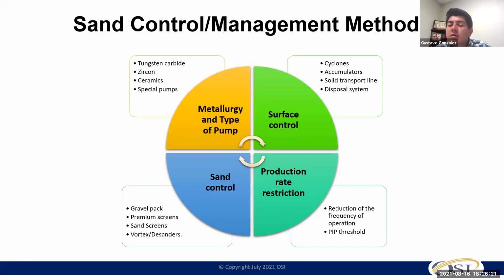Sometimes, based on where your perforations are located, I can raise up my pump to start producing enough. I have enough submergence. I can maybe stop dealing with solids at that point and just allow those to fill that bottom hole section until a point that is economical for me to go back, pull the system, do a clean out, and come back again with a new design.